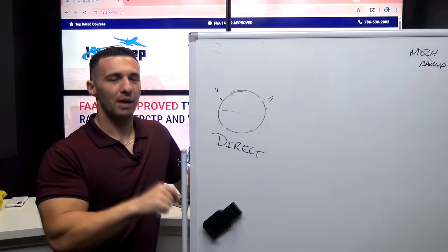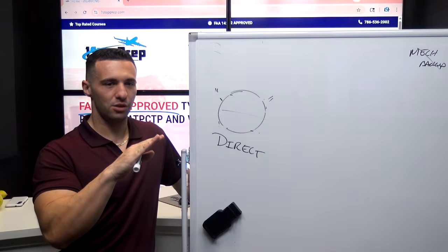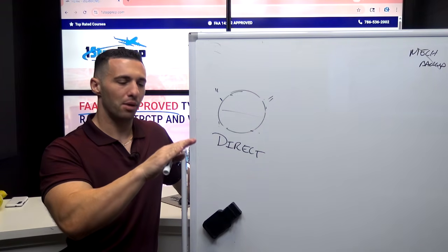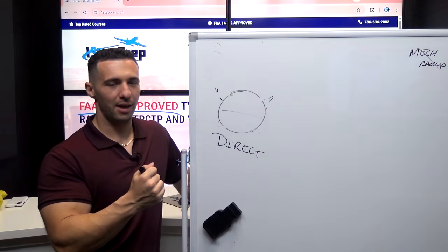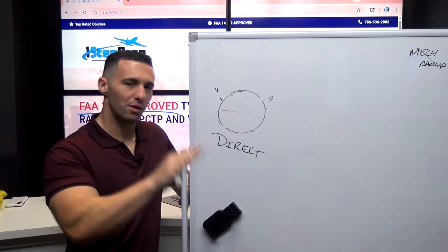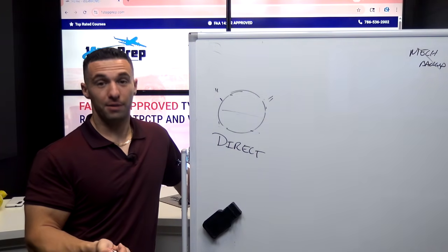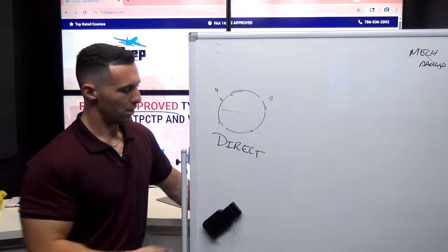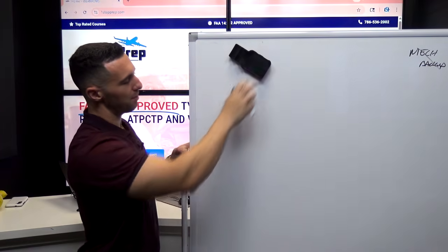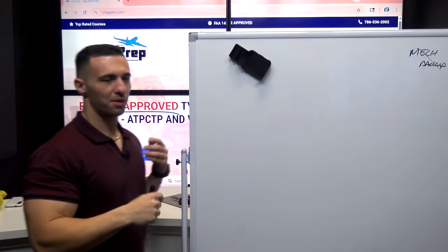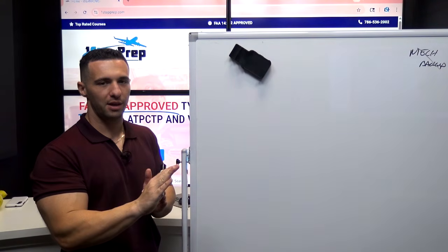flight mode. And flare mode is where the airplane at 50 feet takes a picture of the pitch attitude so that at 30 feet it can begin applying the nose down pitching moment that allows you to begin to apply the aft input to counter the nose down pitching tendency that will ultimately lead to it feeling like a normal flare and landing. It starts at 30 feet because if you read the flight crew training manual, at 30 feet something else happens, which is it commands us to reduce the thrust to idle. Retard. So that's when the thrust gets reduced. That's when the flare formally gets initiated.